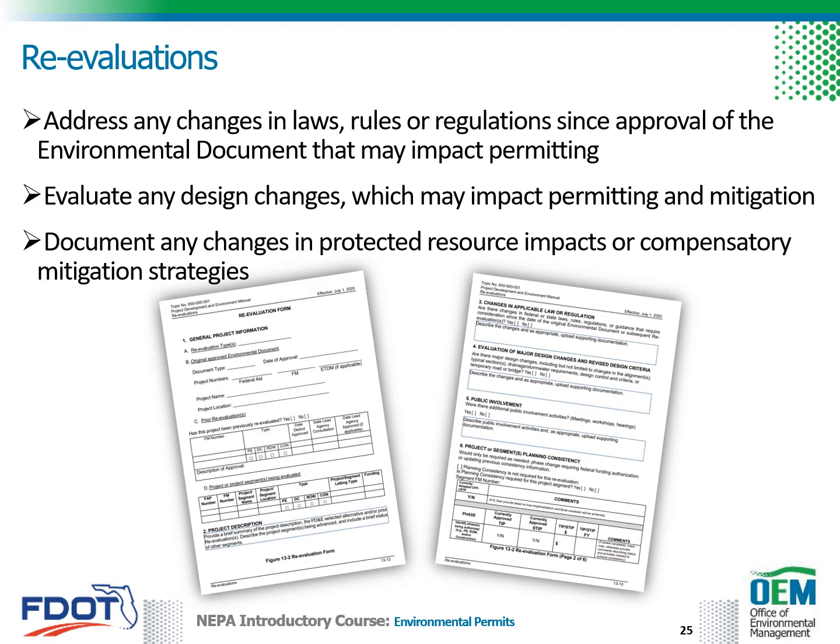The permit coordinator also provides documentation of any agency consultation, such as Section 7 Endangered Species Act documents, a list of permits with issuance and expiration dates, mitigation status, as well as commitment status updates related to natural resources. In some districts, the environmental office will conduct the natural resources surveys or species consultation.